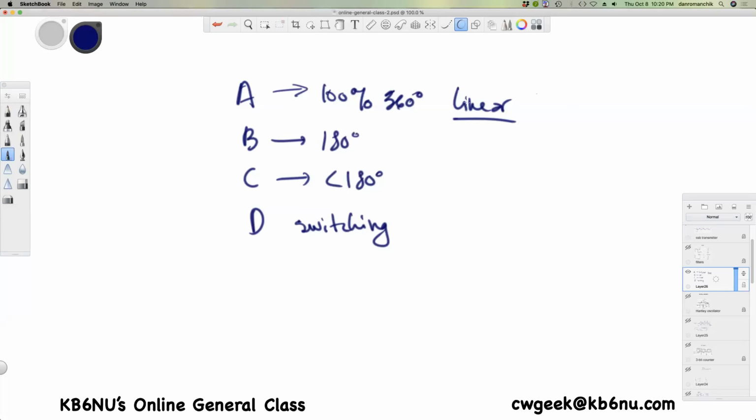The problem with the Class A amplifier is that it's not as efficient as the B or C, okay? The C, in a way, is counterintuitive. Since the active component is active for less than 180 degrees, you think, well, what good is that? Well, it actually is really good, because it's more efficient. This is the most efficient of A, B, or C.